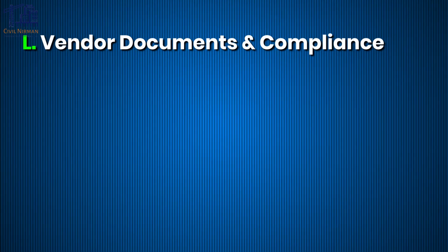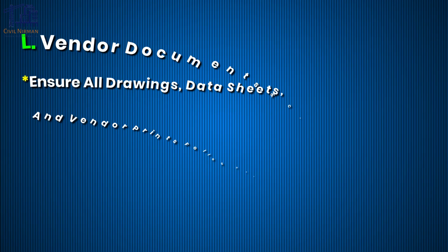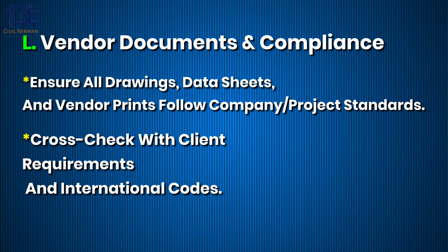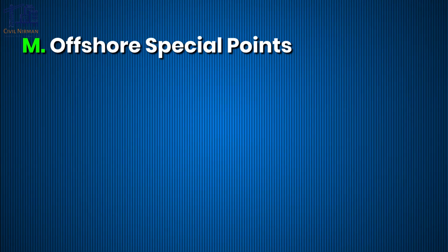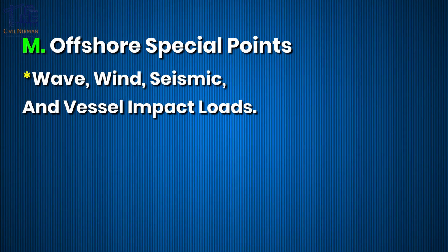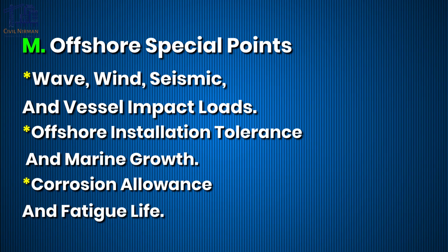Next important part is vendor document and compliance. Ensure that all the drawings, data sheets and vendor prints follow the company and project standards with the latest revision, and you have to check every time you receive new vendor data whether the loads have changed or not. If there is an impact in your design, cross-check with the client requirements and international codes. And the last segment is offshore special points. In this case, wave, wind, seismic and vessel impact loads you have to cross-check. Offshore installation tolerance and marine growth, corrosion allowance and fatigue life.